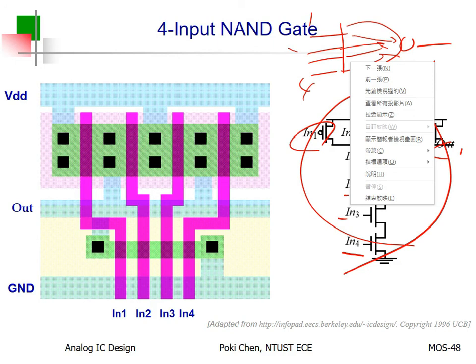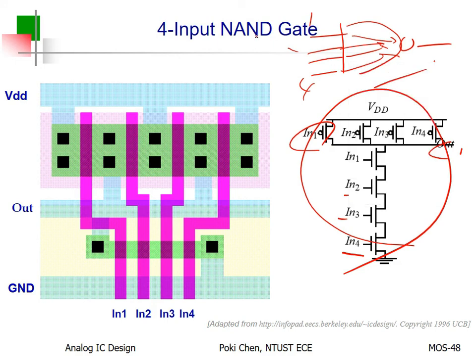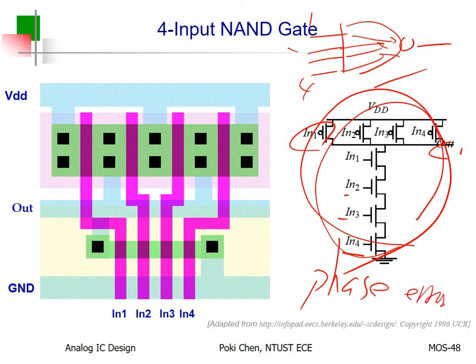Okay? It will hurt your high frequency, for example, PLL, DLL, blah, blah, blah. With such a structure, you will get a lot of phase error. Okay, for high frequency lock loop operation. So what you can do? Again, this is good for digital IC designers, not good for us. If you are a picky, by the way, outstanding analog IC designer, you hope from 1 to 4 to face the same delay to the output.